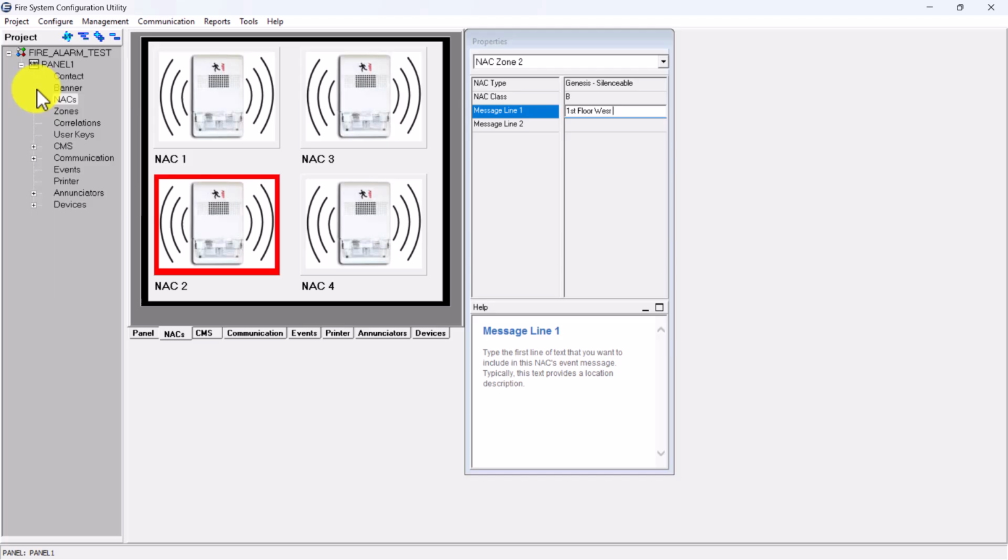And also now we said we want a single input module. We have to go over to the modules tab, and then we have to come down and find a CT1, which is right here. So we got a CT1, we select the quantity of two, we click add device, and we're using M278 pull stations. So we're gonna click on, you see this 278 right here. So we're gonna click on that 278, and we got two pull stations. We're gonna add that device.